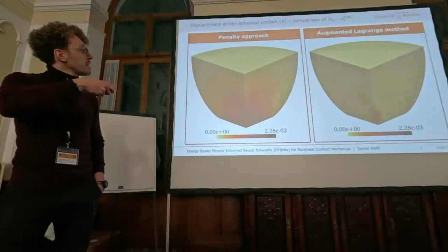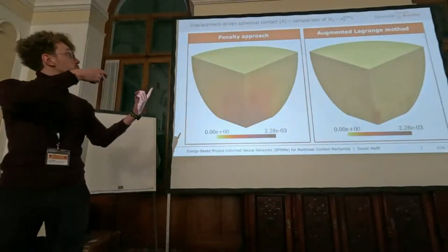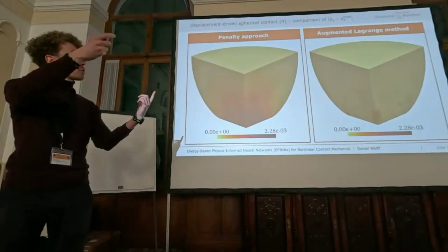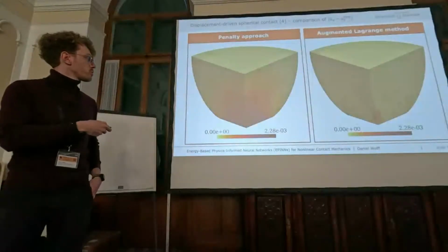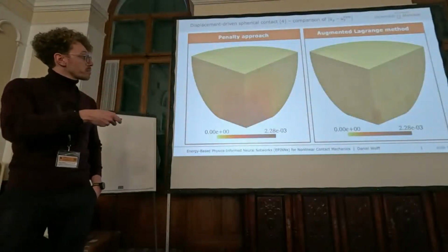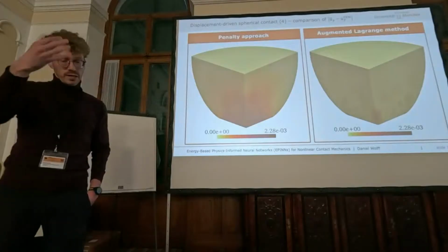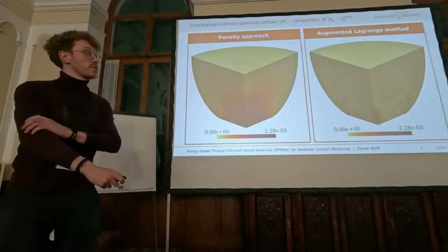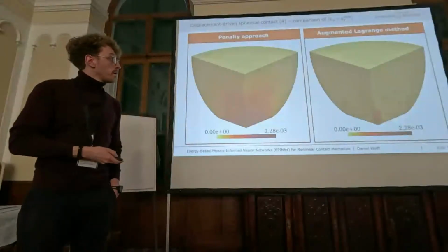So what you see here now is the pointwise error compared between the penalty approach and the augmented Lagrange approach compared to the FEM reference solution. This is now for the Y displacement, and also there we see that introducing these additional Uzawa iterations helps us to reduce the error.